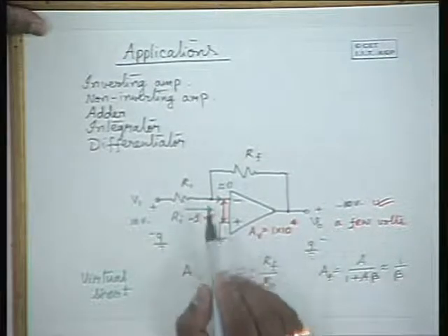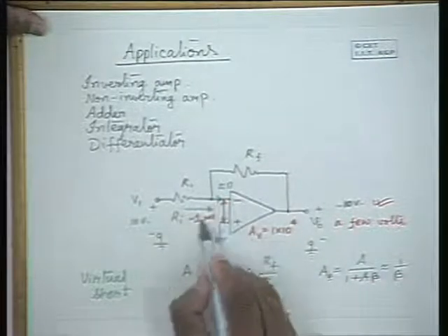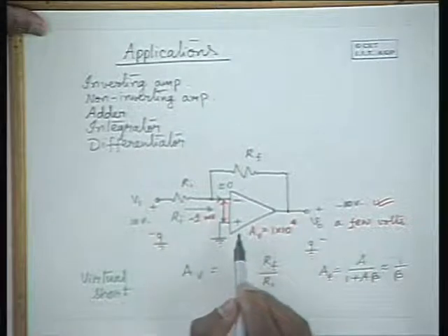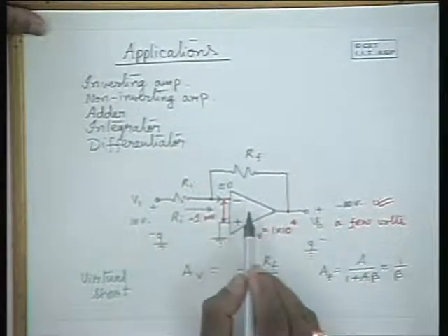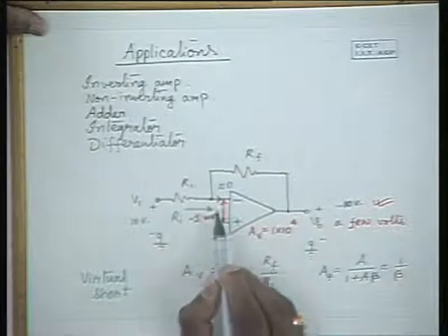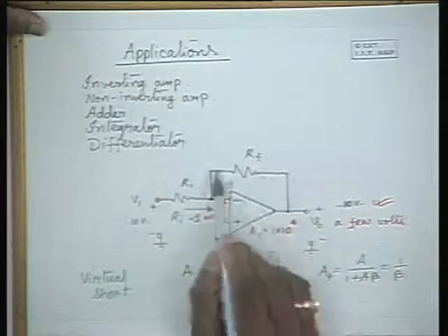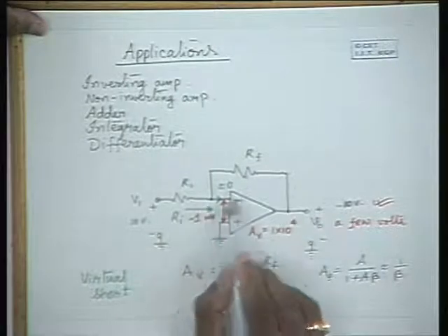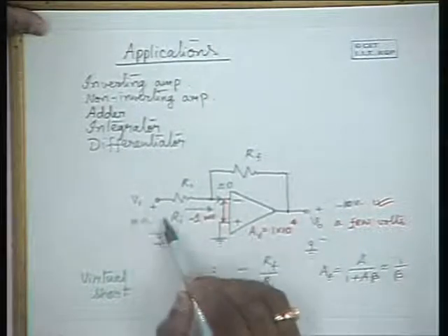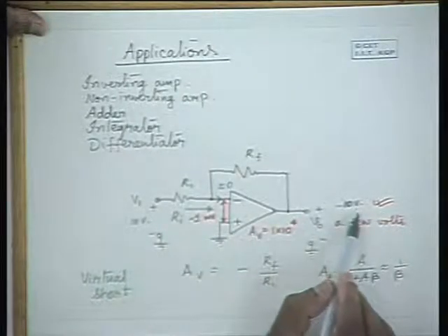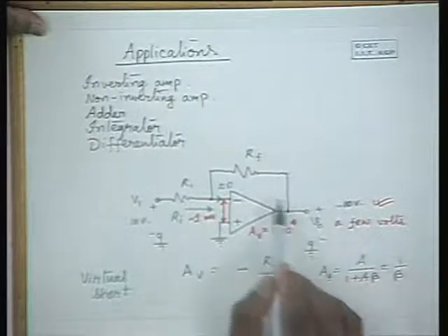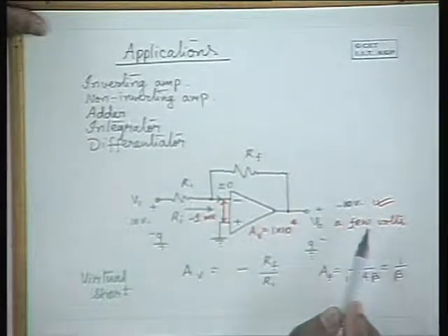How is it possible, and what is forcing this voltage to be such a low voltage? The high gain of the amplifier is forcing it to be of 0 voltage, and partially the feedback is responsible for it. Without feedback, with 10 volts it would have been 10 to the power of 5 volts, and the output would have been distorted.